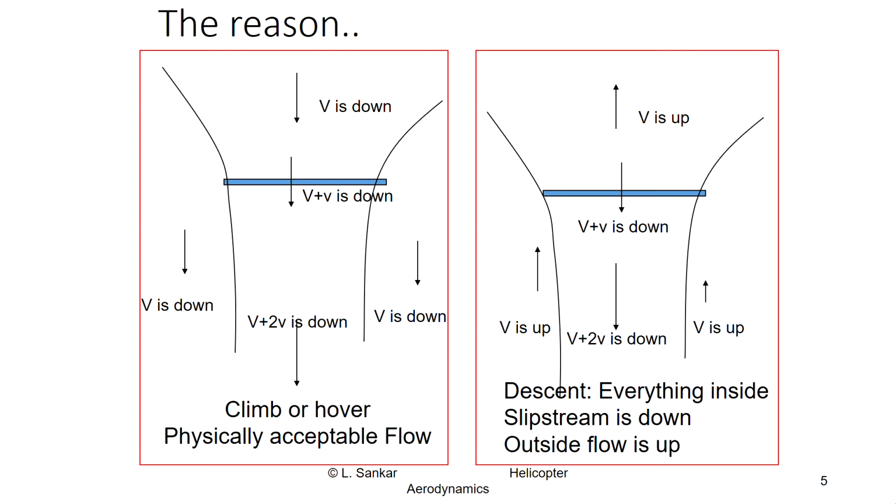Although we see there's a discontinuity in the downward directed velocity in the far wake, because outside the wake it's just capital V, and inside the wake it's V plus 2v. So we produce some kind of a shear layer. Basically the vortex rings that are coming down from the rotor form a shear layer like structure, so it can be visually observed in a lot of experiments.